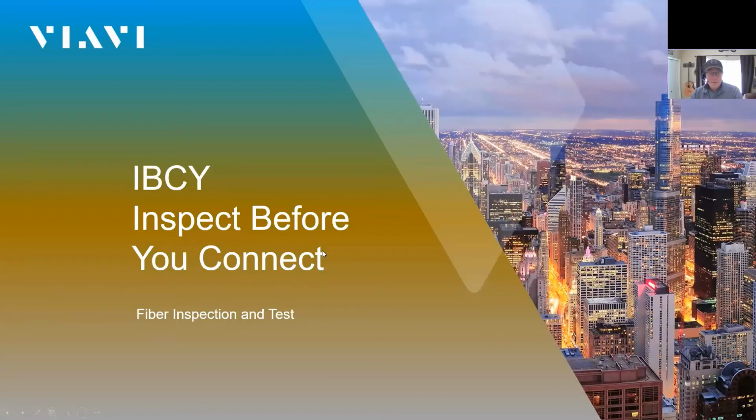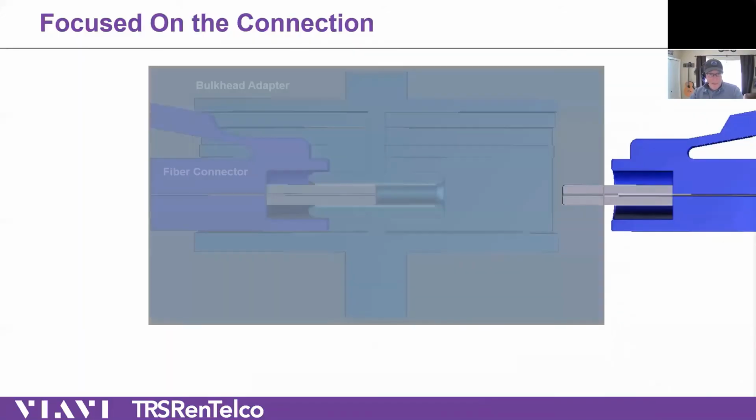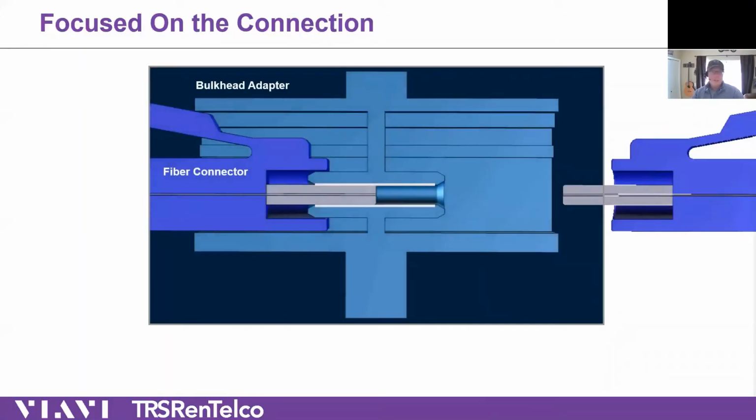So how do we stop that? What's the best thing we do in the next 15 minutes? We deal with the connectors. OTDRs are great. You're going to get them from your customers. You're going to have to shoot them. You're going to have to produce a report. That's just the way that half of these service providers want to work today.